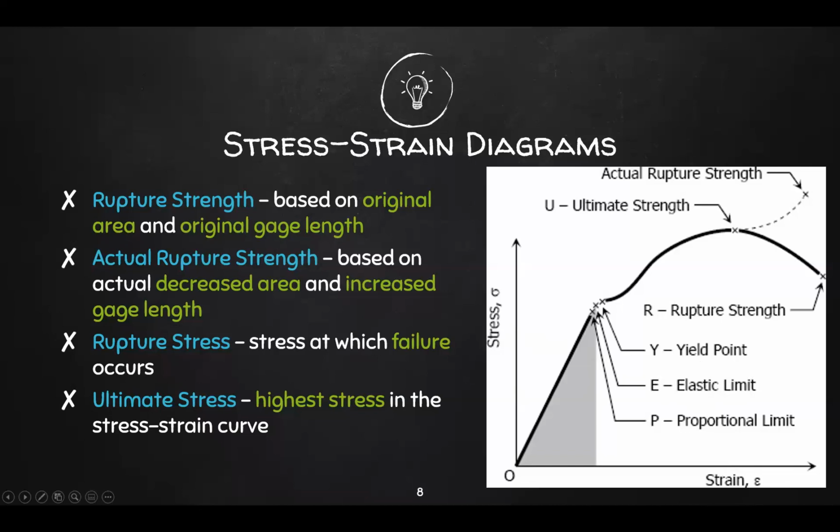And then the end of this stage is your yield point. So it ends here. Okay? And then the yield point is the initiation point of plastic deformation. And the strength component of this yield point is simply your yield strength. Now recall, we talked about yield strength before, right? We considered that the maximum stress your object can withstand.